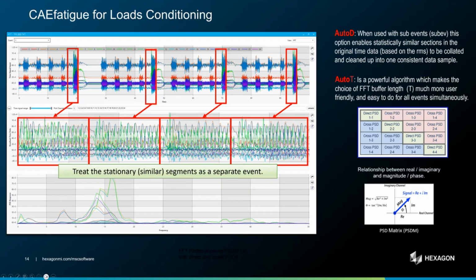So we look at all these signals. You can see that they are not stationary random, they are random at times, because maybe, by the way, it's not even that clear, but you see that you are going around a proving ground, you're stopping, this is 3 or 4 different loops, and maybe it's stopping and then starting, and you cannot convert this into the frequency domain right away. You need to filter out the events that are relevant.